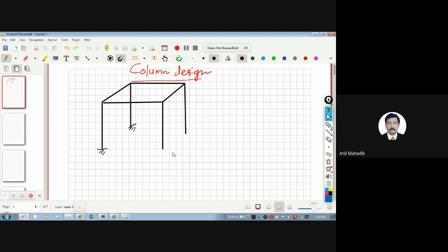So in any structure, in a building especially, this kind of 3D structure, there are loads, all of you know. There are loads on the beams due to slab and walls and their self weight. What happens is there is a bending moment in the beam, and as we consider these joints as fixed joints or rigid joints, there will be fixed end moments like this, and these fixed end moments will transfer into the column also. So whatever unbalanced beam moment is there will transfer into the column.